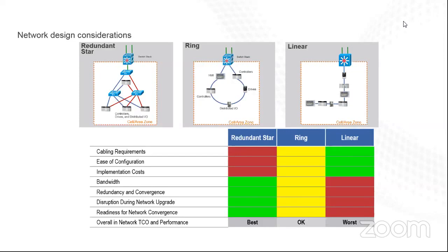And so if you look at redundancy and convergence, and Brandon did a good job of explaining the convergence in a ring network, what we mean by that is how fast can the network repair itself? And that's usually measured in time. And of course, the DLR is very quick. So within 3 milliseconds or so, the DLR ring can come back. Well, a redundant star, because it can retain multiple failures, doesn't have a convergence time after your first failure. So that convergence time would be 0. So that would be another use case example for a redundant star.